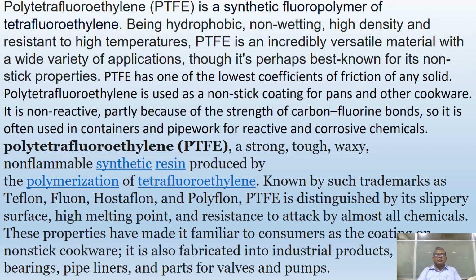PTFE is an incredibly versatile material with a wide variety of applications. It has one of the lowest coefficients of friction of any solid. It is strong, tough, and non-flammable. It is a synthetic resin, and that is an important property. So trademarks are Teflon, Fluon, Polyflon. So like that, different names are commercially available. It is also fabricated into industrial products like bearings, pipe liners, and parts of valves and pumps.